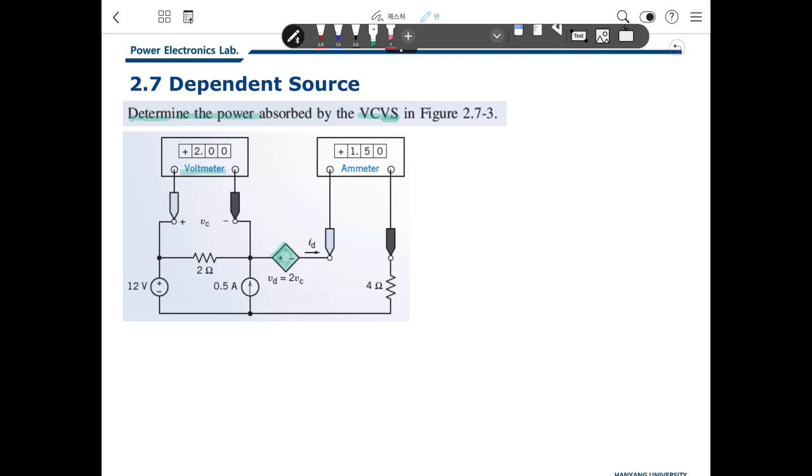This is a voltmeter. It means in a voltmeter, the path between the two points is open. So this is open, which means there is a very large, infinite resistance, so the current flowing through it is 0. In the case of an ammeter, this is a short circuit, so the current flows this way with no voltage. In this case there is 0 voltage difference. That is the characteristic of an ammeter, and this is the characteristic of a voltmeter.